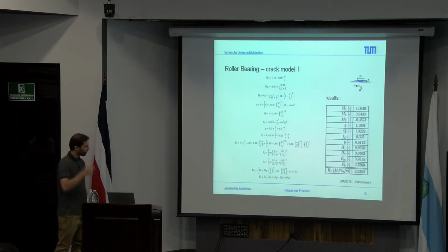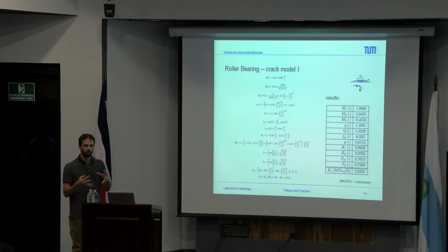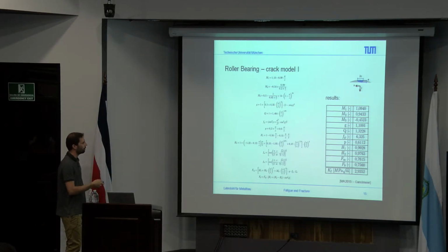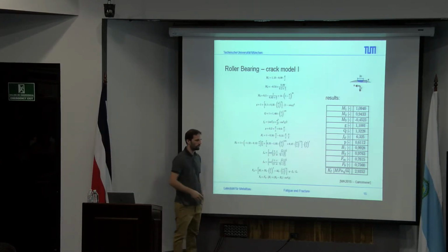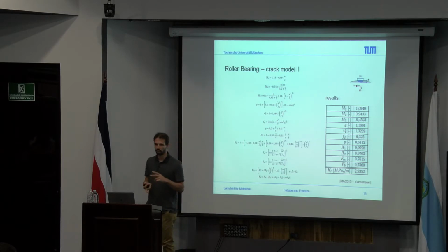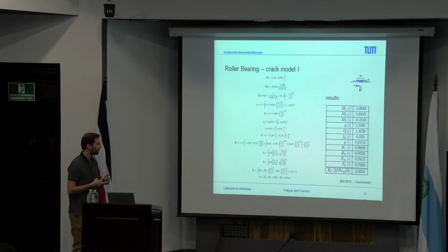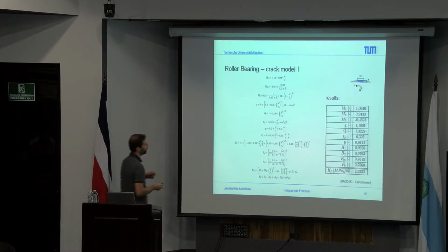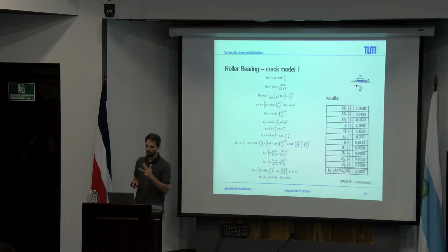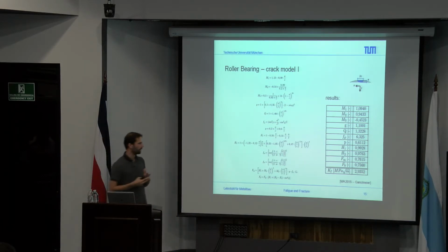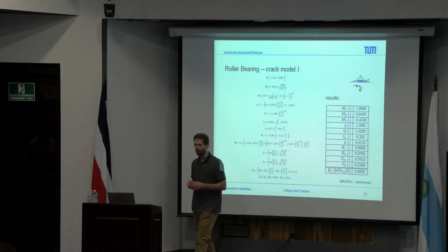At the end, due to the surface model, you see here just the basic calculations. These are formulas you can find in the FKM and in some guidelines of the IAW. Due to the description of the crack size and the applied stresses, you get in the linear elastic behavior the K1.